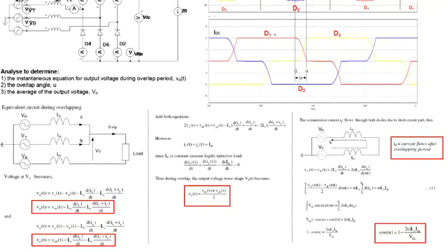So if you consider D1 and D3, the current that will flow after the overlapping period is actually through the yellow phase. So you must follow the yellow current direction, not the red current. If you follow the red phase current, you will be clockwise. But now, because after the overlapping period the yellow current will flow through the circuit, we have IU set to follow that direction. Okay, so having that equivalent circuit, then you solve for KVL around the loop.